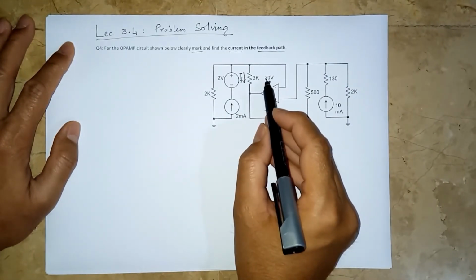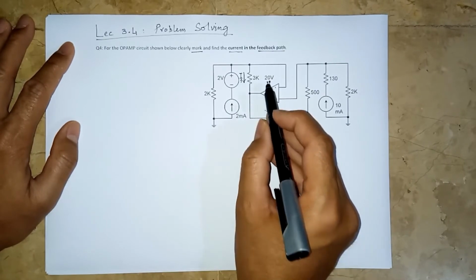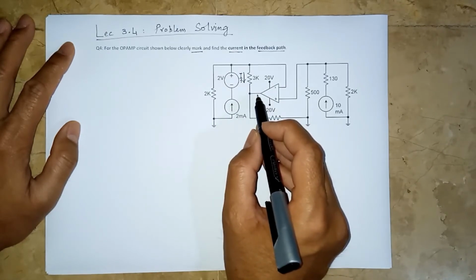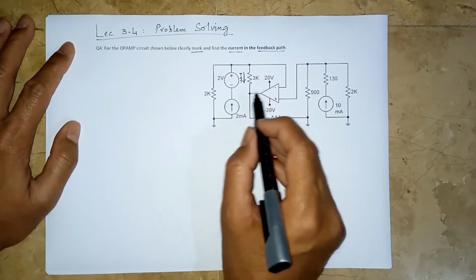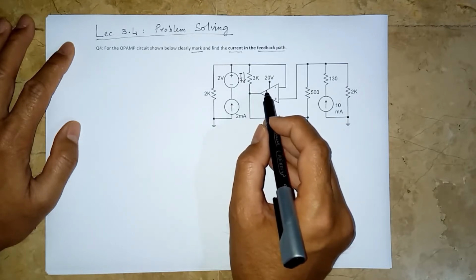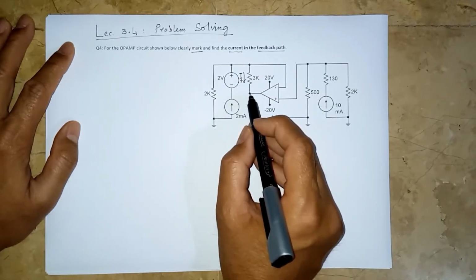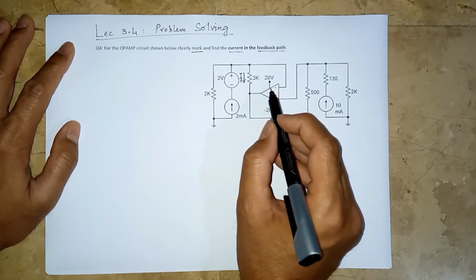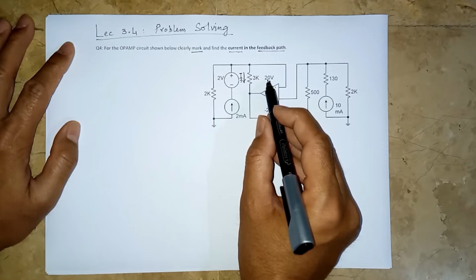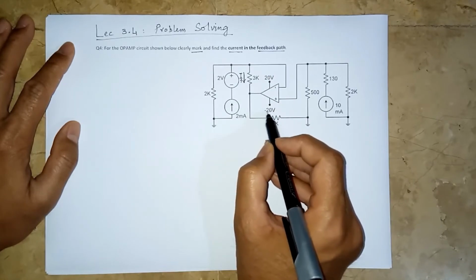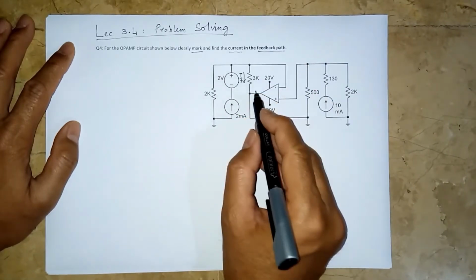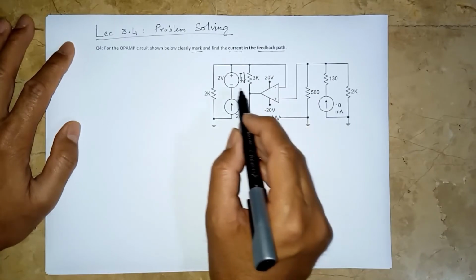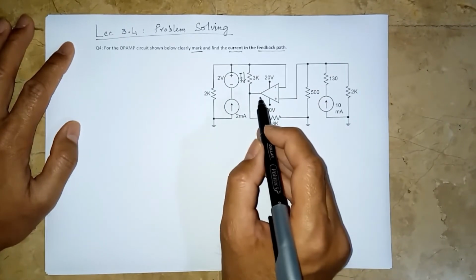In this circuit, you can see this 20 volt and the minus 20 volt. These are the two supplies that power up this op-amp. When they are given, we need to check whether the output voltage must be within this range. But for now, you can ignore this. But let me mark that the output of an op-amp must always be between this range. We will study this later when we study saturation. When the op-amp saturates, its voltage cannot go beyond 20 volts or lower than minus 20 volts. So the output has to stay between this. In this part, we say that the op-amp operates in its linear region, and that is where the linear circuit analysis applies.